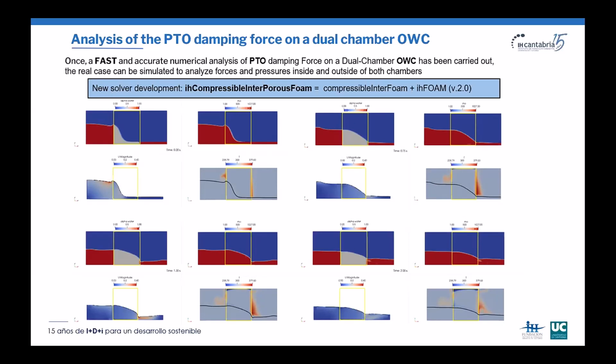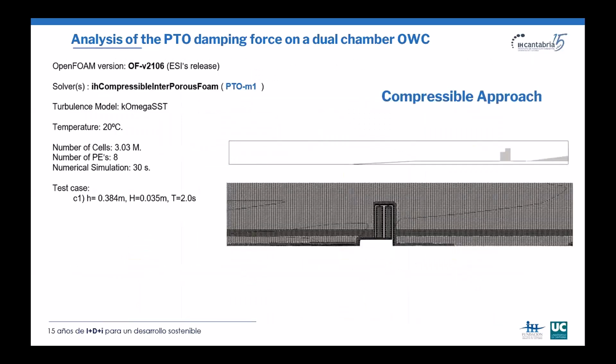Once we have done that, what we have done is add the porous medium solver to the compressible solver in order to be able to solve real experiments. So we need to add the porosity in order to replicate numerically this dissipative beach. It is important to realize that we know the Forchheimer equations are not perfect because they don't take into account the temperature, but this is just a dissipative beach. So they're just going to be, let's say, eating the waves.